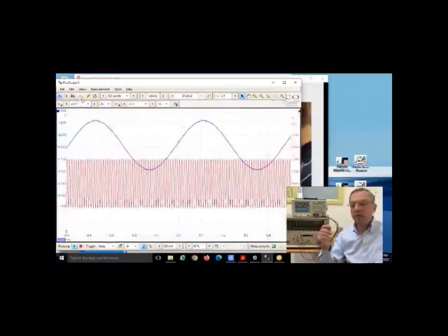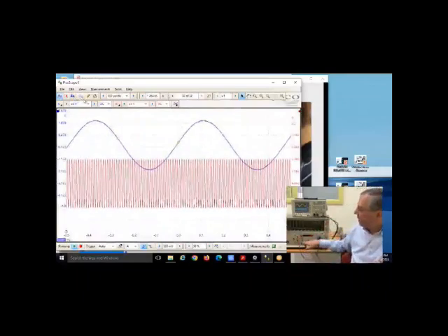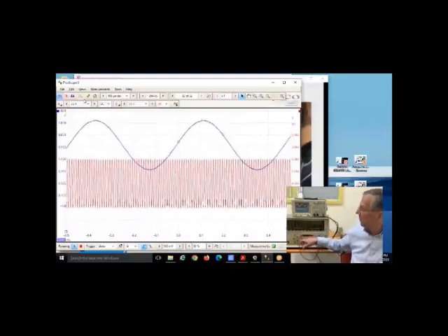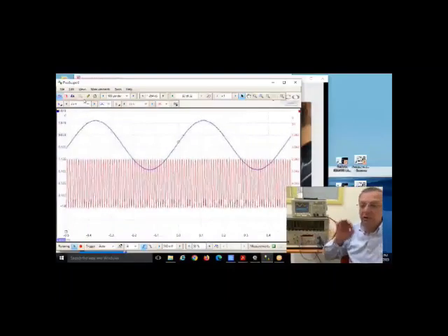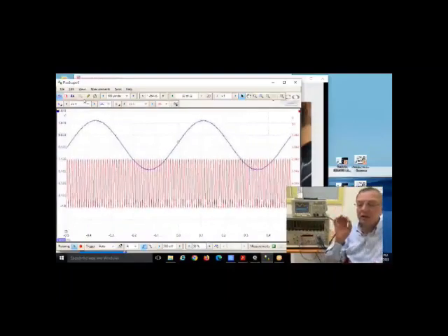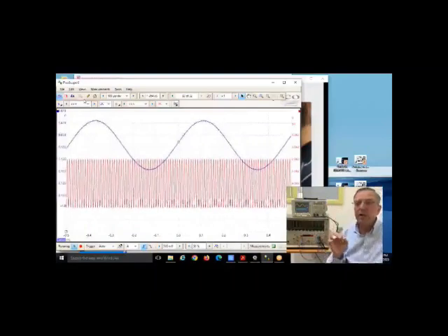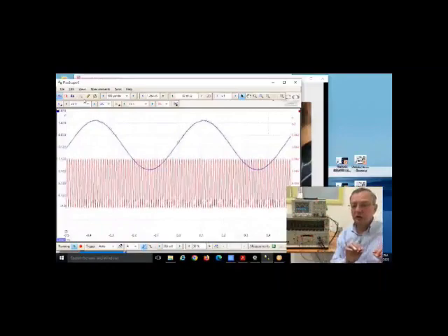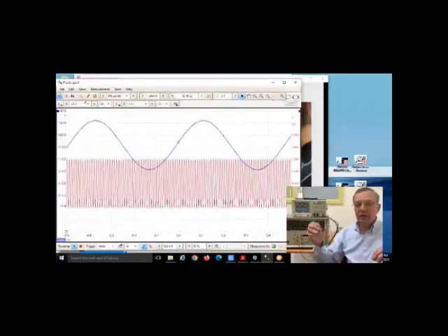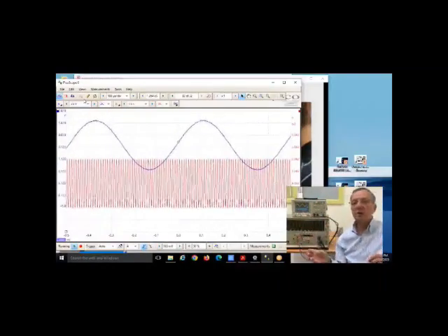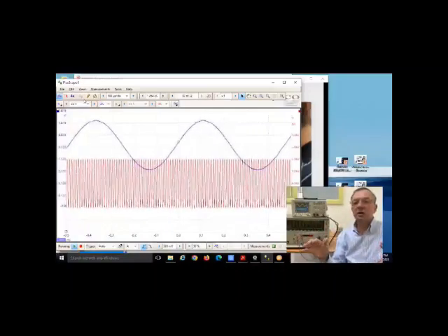And most importantly, as I mentioned briefly, this 2 kilohertz message, the 8 kilohertz sampling signal, and the 100 kilohertz signals are all synchronized. This means synchronized in a telecommunications sense, not in a digital electronic sense. In telecommunications, synchronized means that the phase relationship between the signals is constant.